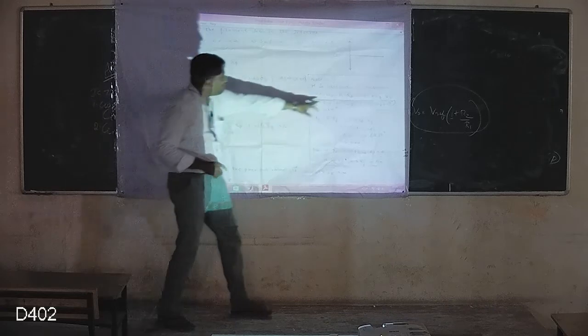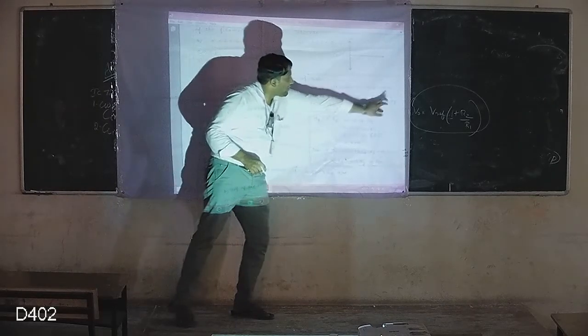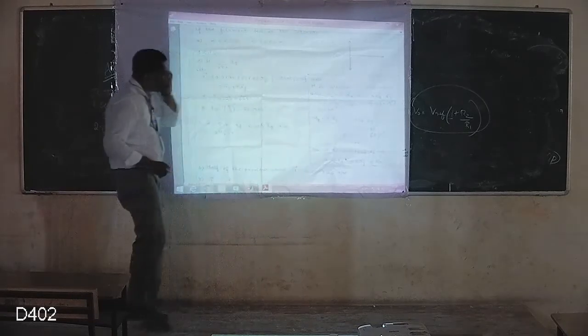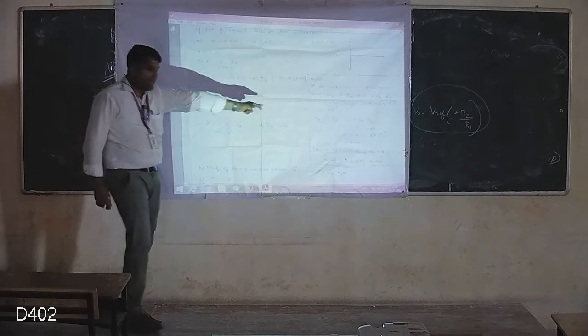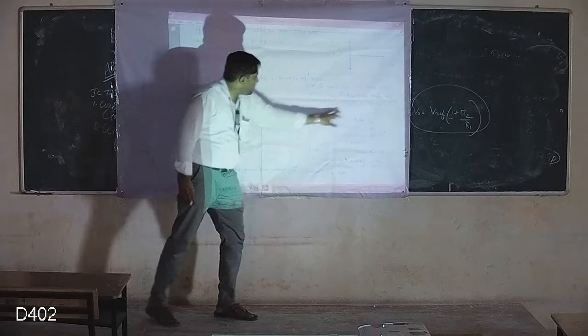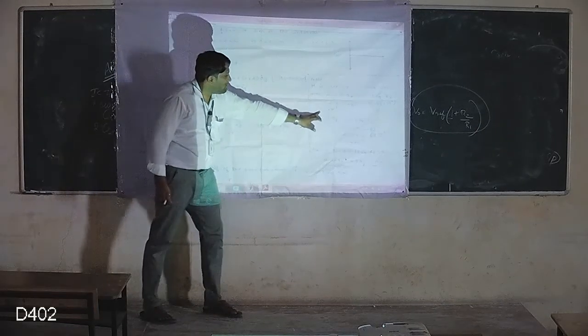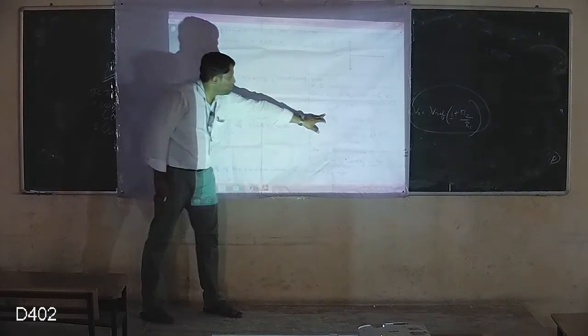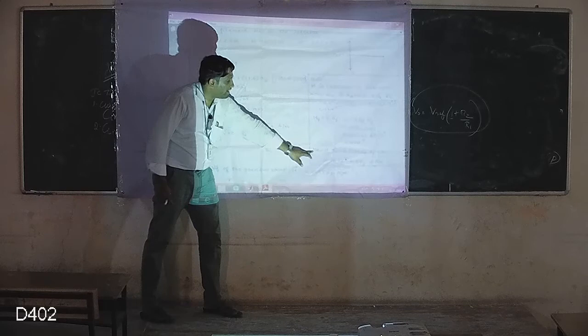Hence, we write the H vector we obtained in the direction of a phi dot ax. A phi dot ax happens to be minus sin phi, and phi is evaluated here. With this substitution, we will get the answer as minus 11 into 10 to the power of minus 3, and similarly we will find Hy and Hz.